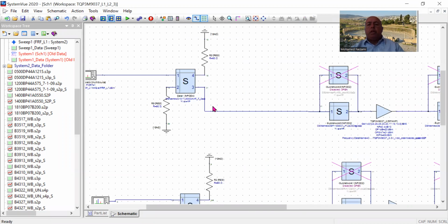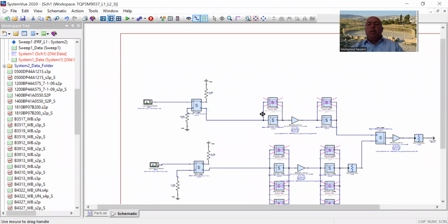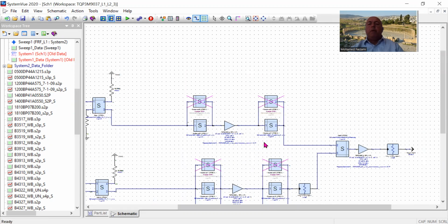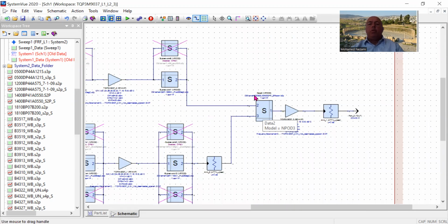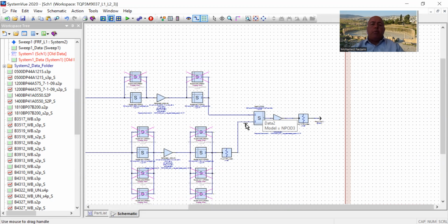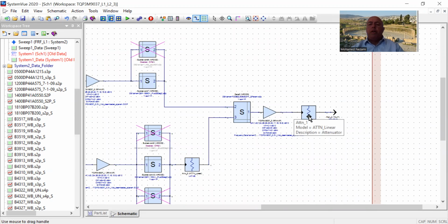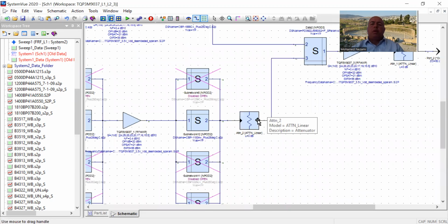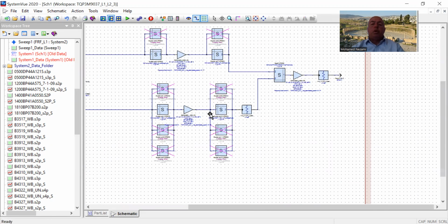Then, of course, we take this signal and filter it first to reject all the interferences, and then amplify it, and then filter again to reject the interferences and strong nearby components. Then we go into a two-way combiner where we combine the other branch, which is the L2 path. Then we amplify, and finally we go into the final output. To equalize both sides, I've included a variable attenuator in here, which we can set up using a bi-pad of 3 resistors, so as to equalize the paths.